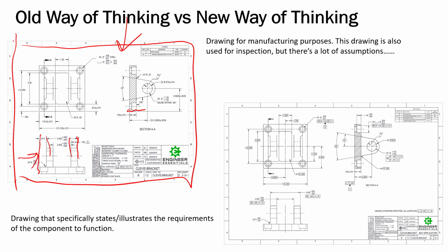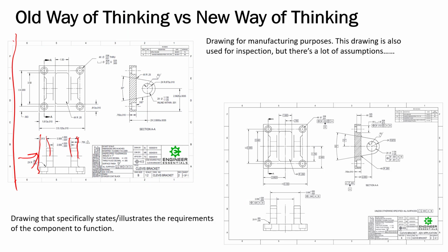But like I said, also we are supposed to be opening up those tolerances if we can do it. Do a little bit of homework, see where you can go back in and open up tolerances. Like I said, this should not affect the manufacturing processes at all. If anything, it should make it easier with using GD&T, provided that the machinists know how to interpret this GD&T.